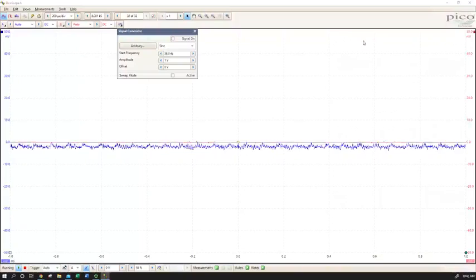So that is it for this demo video. Hopefully you've enjoyed deployment of the concept of resonance and a picoscope to identifying some component values using two different principles. And feel free to try that. Also, if you have a known value of an inductor and need to test a capacitor, the same principle would work. So if you can't read the teeny tiny markings on a particular capacitor, this may be an easier way of identifying it than hunting for a magnifier.